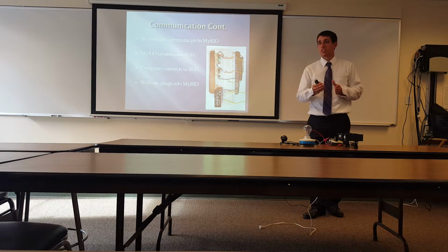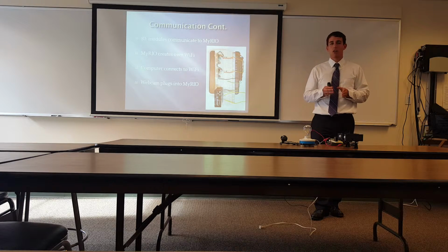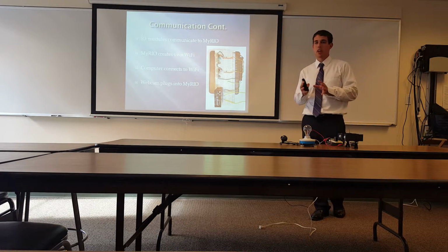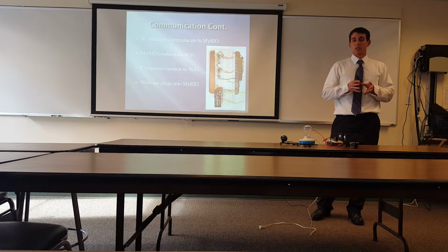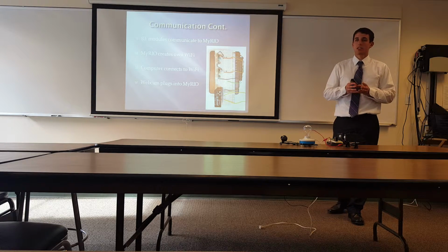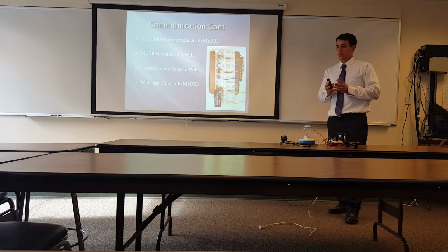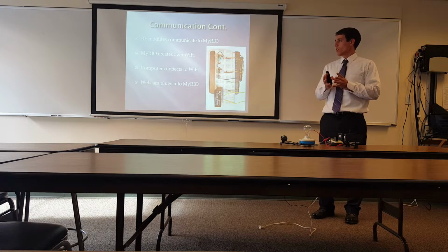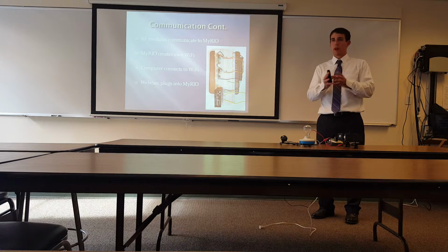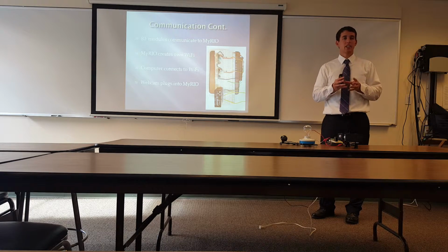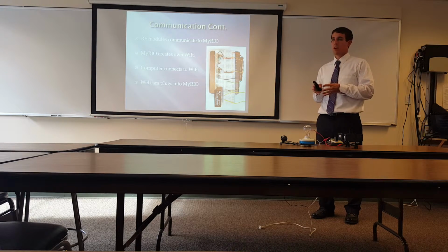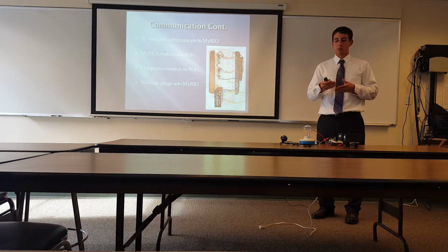So the next communication part is the myRIO. The RF modules will communicate back to the myRIO. Another feature of the myRIO is that it creates its own Wi-Fi. So you can deploy the myRIO in a separate room, since the webcam has to be plugged into it, and then you can connect to it through your computer from a different room. So you don't have to be constantly plugged into the myRIO.